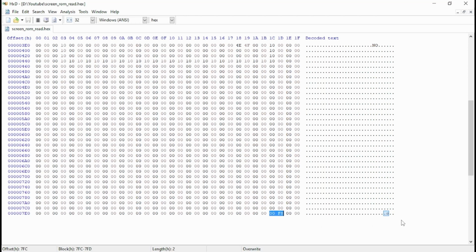The CPU is what is known as little endian, which means it reads numbers in the reverse way round to how we have them in decimal, i.e. lowest number first and highest number last. So 00F8 becomes F800 for the start address. If we don't put that in the top of the ROM, then it won't know where to go on the reset sequence.